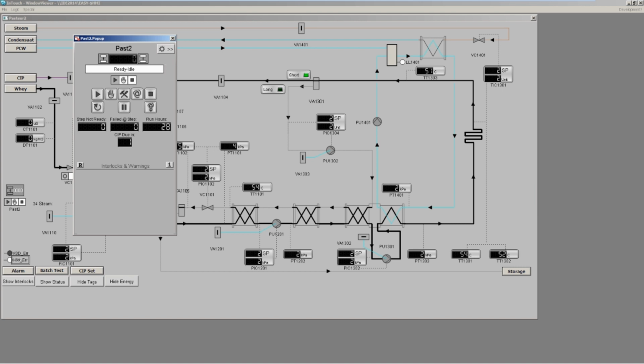In the PLC Easy solution, any hardware diagnostic signal from any type of device, could be a legacy device, could be an Ethernet switch, could be an I/O card, could be a vendor's kit. In short, any device that has an indication that there's a problem can be incorporated into the PLC Easy alarm management system. In this example, we're going to show an I/O card failure, and the operator is notified of all the signals that are connected to this I/O card and are therefore unreliable.